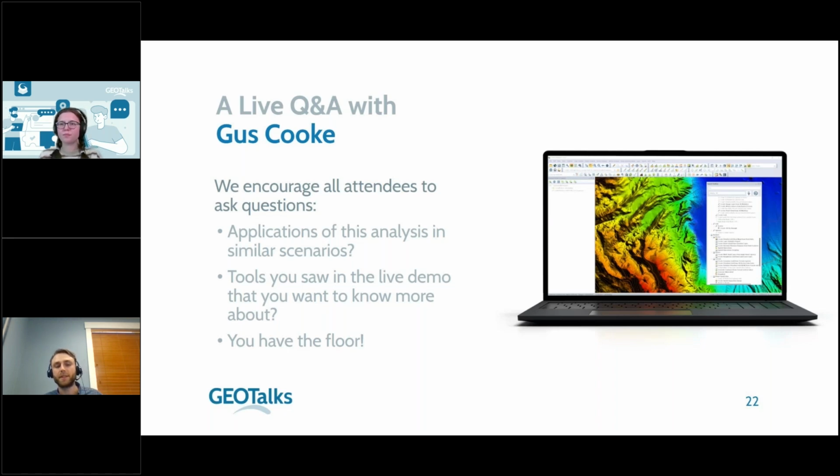It doesn't need to specifically be elevation, but you can load it in, and Global Mapper will treat it like elevation, which allows you to perform elevation-specific workflows on that raster data, regardless of what those Z values per cell represent. And in terms of the second question, yes, you can use 3D vector features as obstructions within the solar analysis tool.